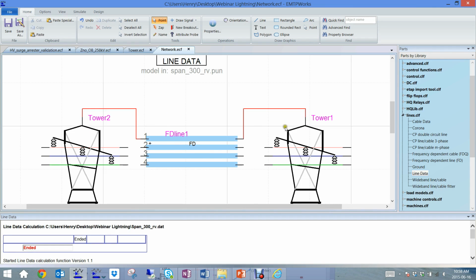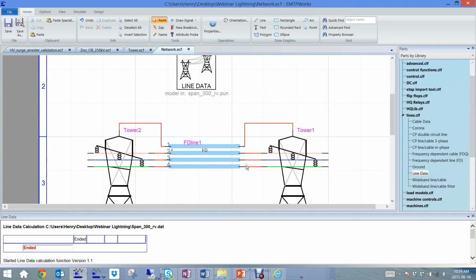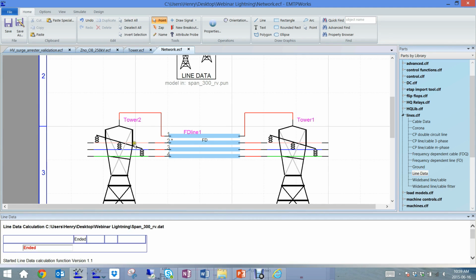Okay, so the lightning will strike one of these towers. So I connect them. Locally, where the lightning strikes, it's good to model each span, because what can happen is there's going to be a back flashover or flashover, and in that case, you have to model a tower. You model as many towers as needed. The point is the last tower you model shouldn't have any back flashover. So it's kind of an iterative process. You run your simulation. Here there is a flashover to the last one, then you have to add new ones. But usually if you put 4 or 5 of them, it's enough.